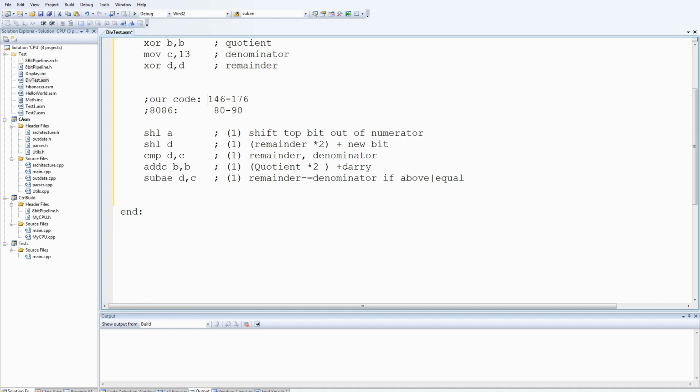So that would be 40 to do it on an 8-bit register and 80 cycles plus whatever extra little bits of shuffling we need to do to make it into a working function. So probably we'd get very close to or beat the 8086 if we can make this work, and that's dependent on working out a way to create this instruction. But this shouldn't be that complicated. So let's see if we can add that.